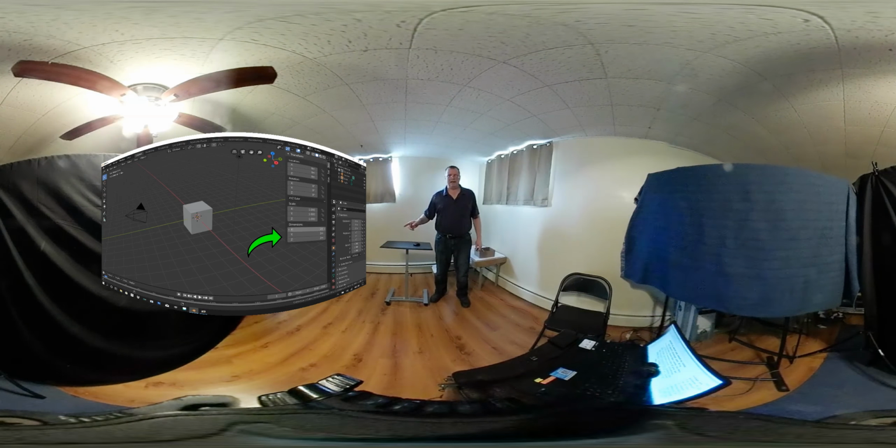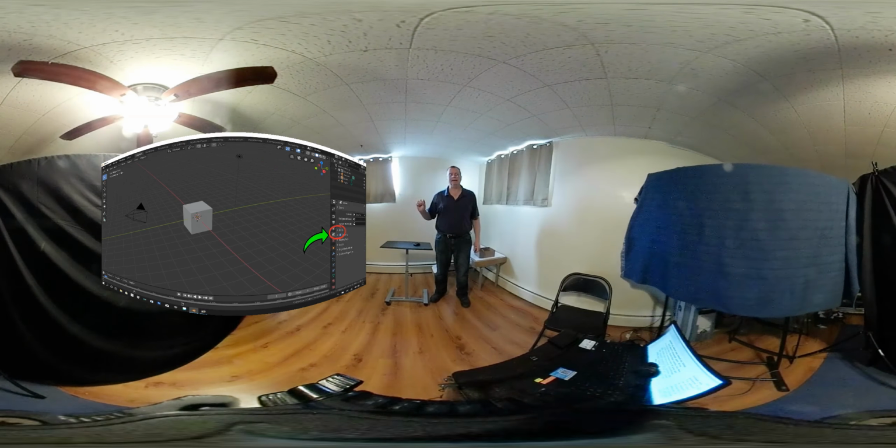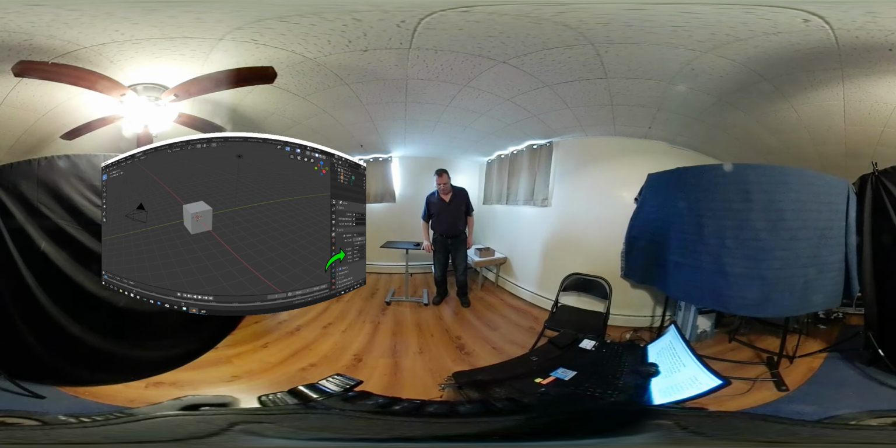So you'll notice off to the right-hand side, there's a little icon. It has like a cone and 2 circles in it. That is the scene context. And so if you click on that scene context, there are several items off to the right-hand side with a little arrow that you can drop down more information. And so it's just a little off to the right and up. You'll see the units drop-down menu. And you'll want to drop down that menu because there are a couple things we have to cover with that.